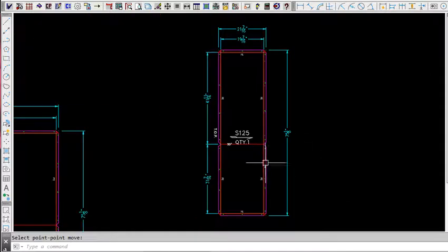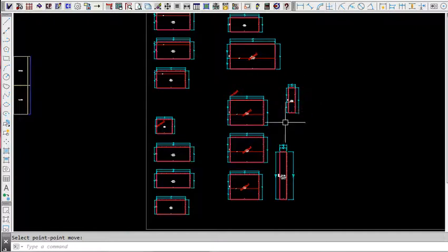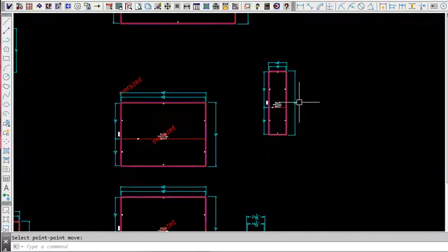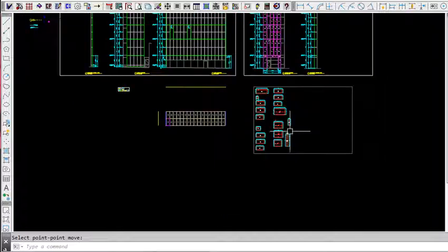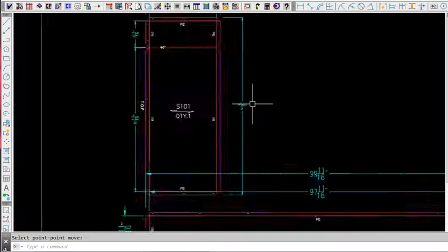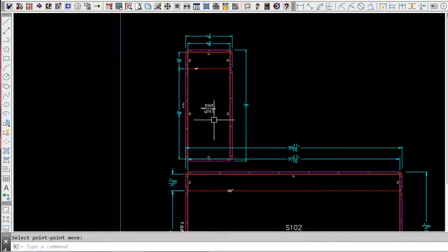Okay, so these panels, the grain is going left to right, and it's an outside corner, so it's 175 inches tall, and that's a bad one, because it needs to really be going horizontal. So that S125, even though it looks right, it's not, because this is the way it's going to sit on the CNC, and 75 is too wide. So how you would adjust that, and I think we got, no, this one actually fit in there, so that one would be okay.